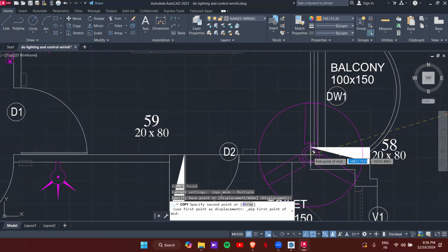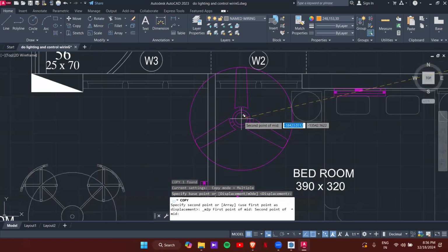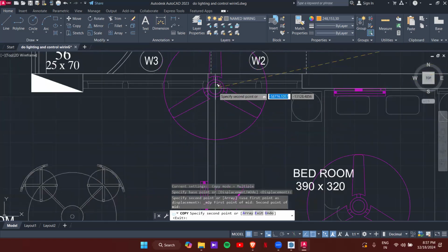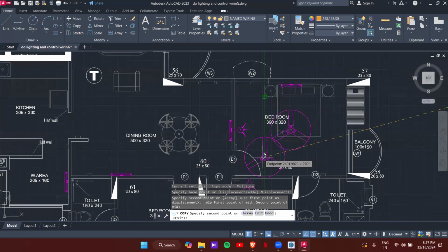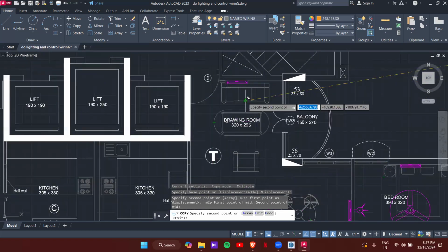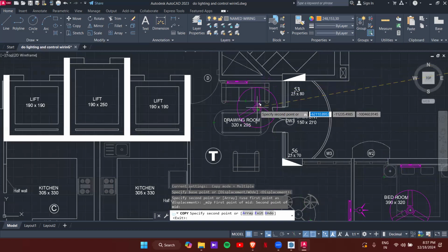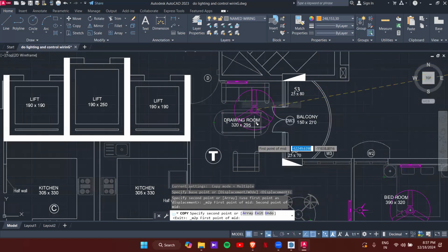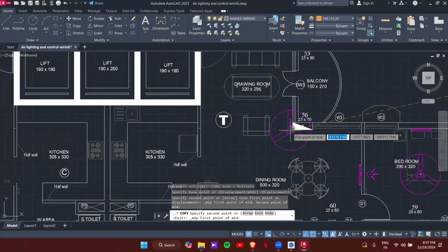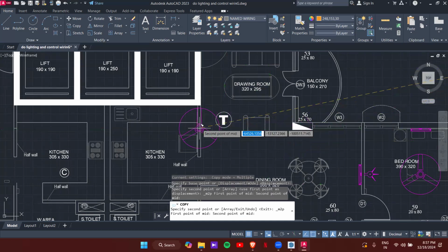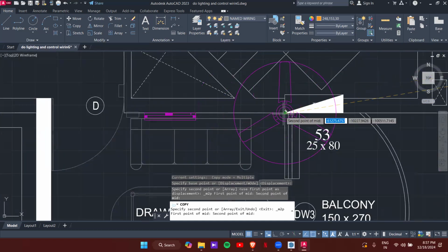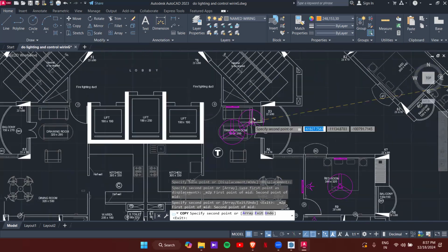Now just click here and the opposite corner. So see, that's how you place it. Similarly, over the dining room as well. Mid between 2 points. Again, this is the ending point, right? So just drag the first point here, and second point over here. Okay, so that's it.